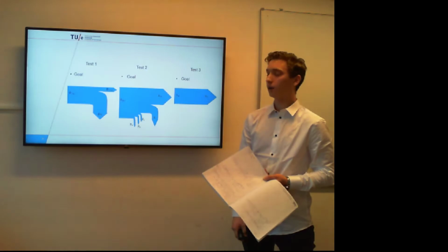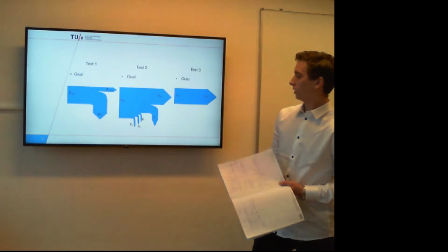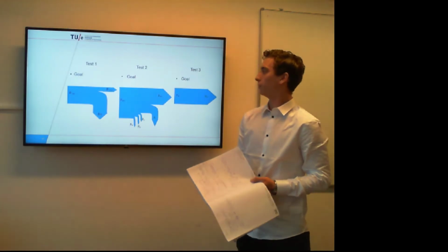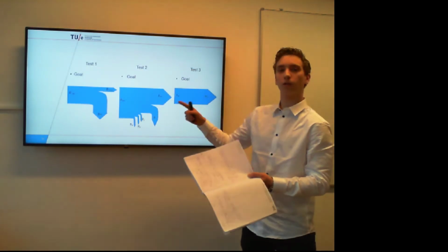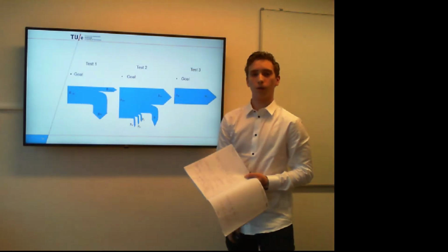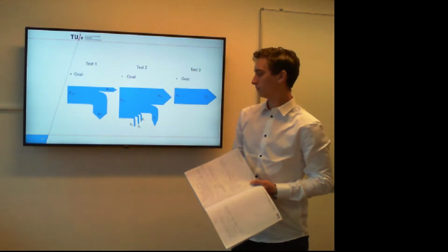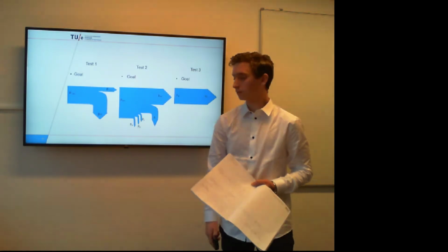Then we've done test 3, which will enable us to measure the energy usage of the electrical components. With all these 3 tests, we can subtract test 1 and test 3 from test 2, which will give us the values of PG, the power loss of the gearing, and the power loss of the motor.